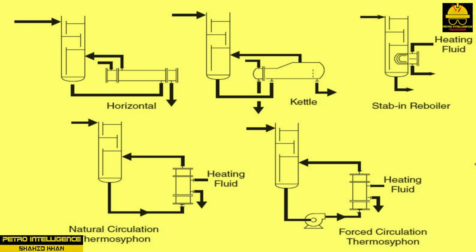A pump is not connected to the tower and exchanger. This system uses buoyancy forces to flash off and pull in liquid. As vapors are flashed off into the tower, the suction line draws in an equal amount.